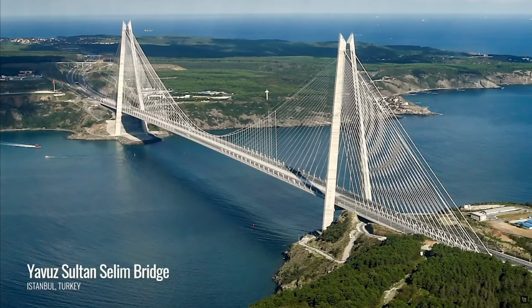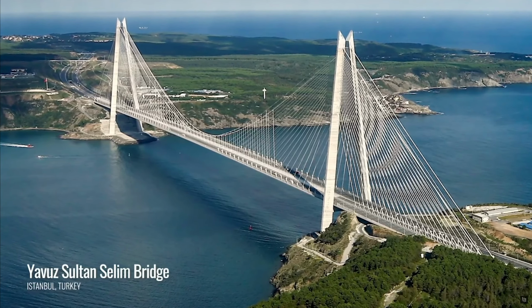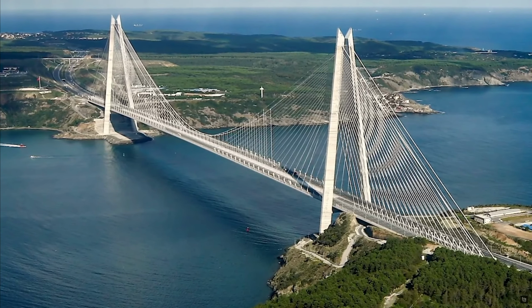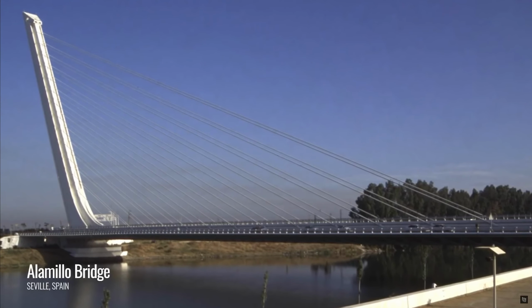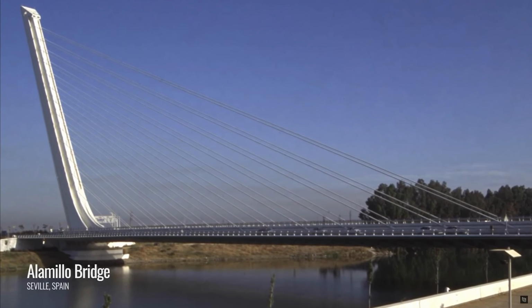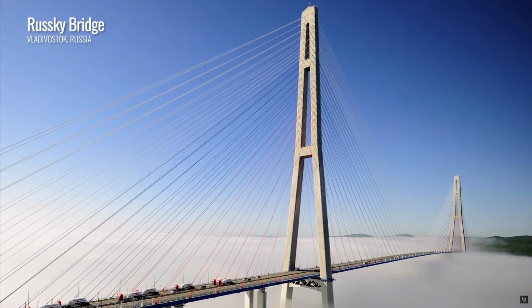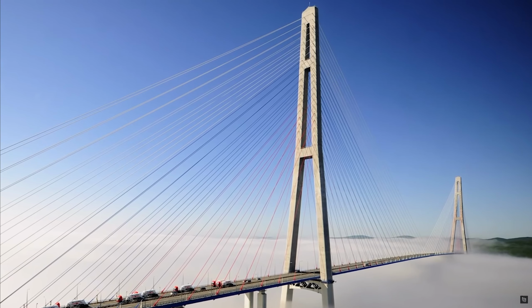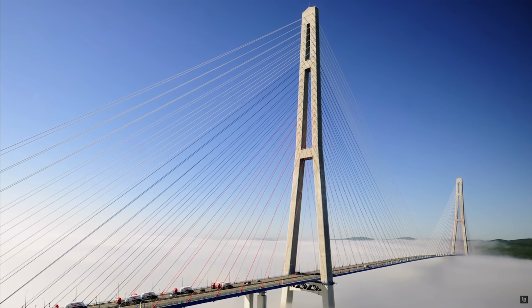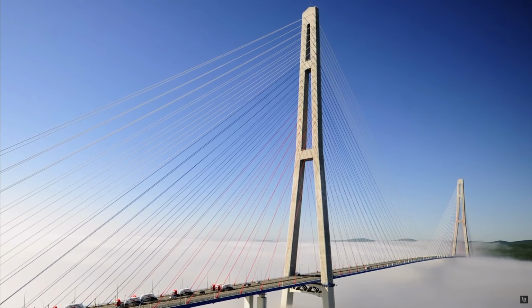And so this is not only helpful in the way that the bridge remains in equilibrium, but this is also something that many have used to their advantage throughout construction of those bridges as well, by holding things in place as things are being built. What it allows you to do is use cables to act as a resisting force to the suspended or hanging deck. Because the deck in and of itself is not required to have anything beneath it, your cables are able to go much, much longer than you could fabricate anything else to serve as a superstructure. So, cable stayed would be really useful for long or tall bridges.